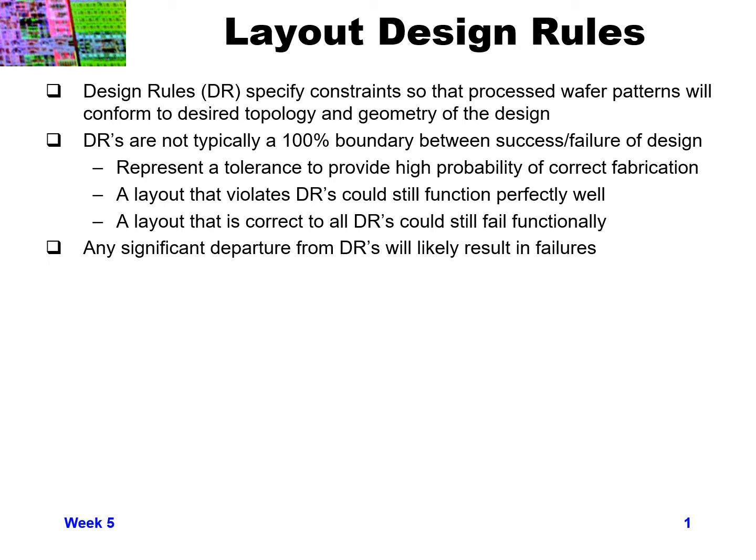You created a new pattern that wasn't predicted and caused some sort of failure because of that. So the main thing that I want to reiterate here is if you depart significantly from your design rules, you're more likely to result in failures and not actually getting what you want on your silicon wafer.